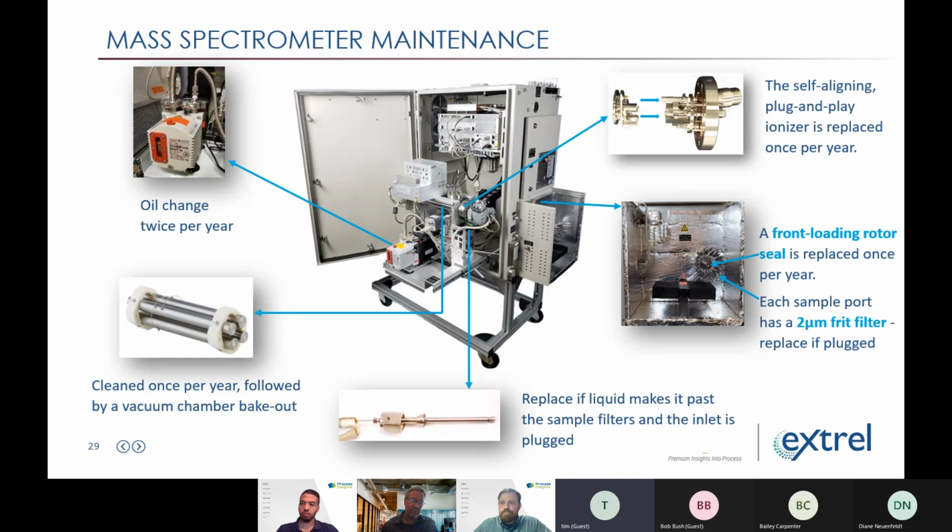And what I kept trying to explain to everybody is you can't use the steam flow measurements below a certain number because it's such a large span. You can't say I'm measuring 70,000 pounds an hour of steam if that's your span and you're measuring 500 pounds. The meter is not going to accurately measure that.